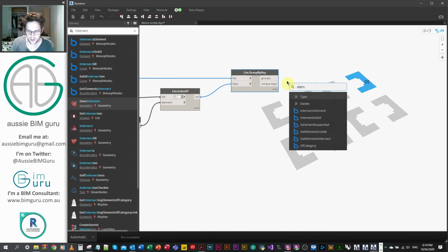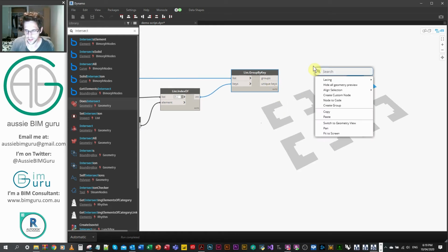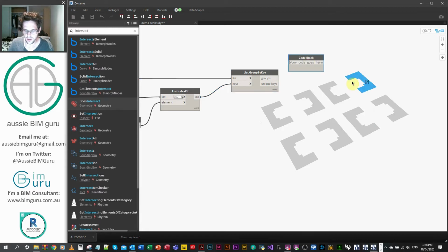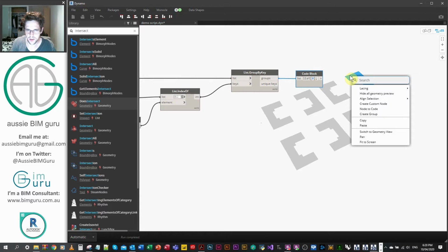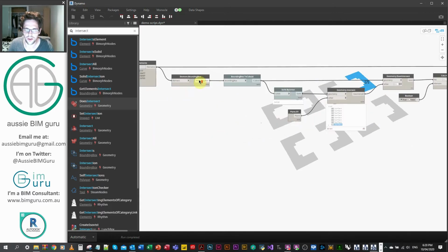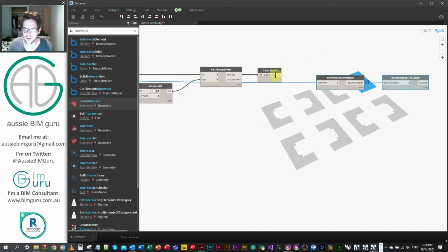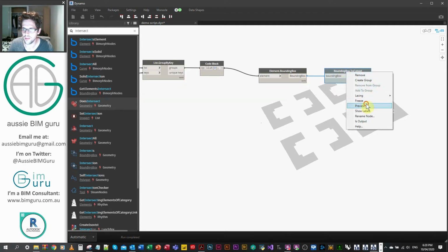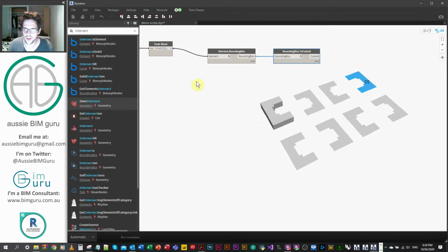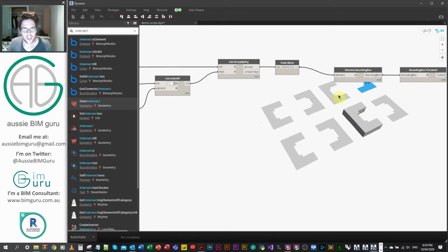And we can really quickly check one of these by getting their bounding boxes. So we could get the list at index 0, and let's just get their bounding box again. So I'll go back and copy some nodes. We'll just copy this bounding box and bounding box to cuboid. And you'll be able to see that we've collected a set of 3D bounding boxes that are connected together. And there you go. You can see that we've got a set. If I go to say number 5, you can see we've got a set. So in this case, we've collected our workstations.